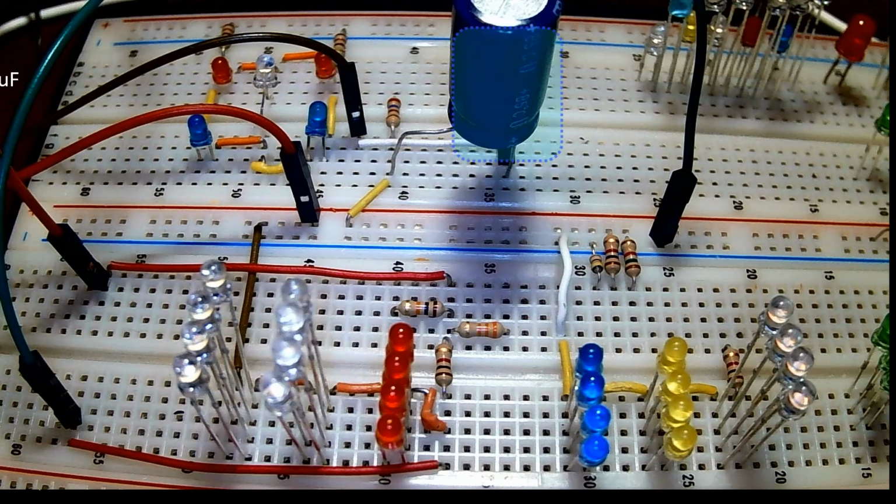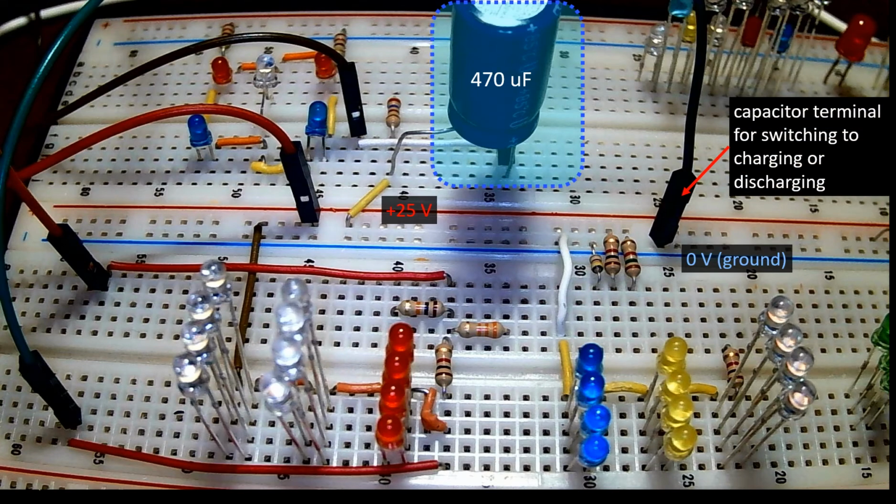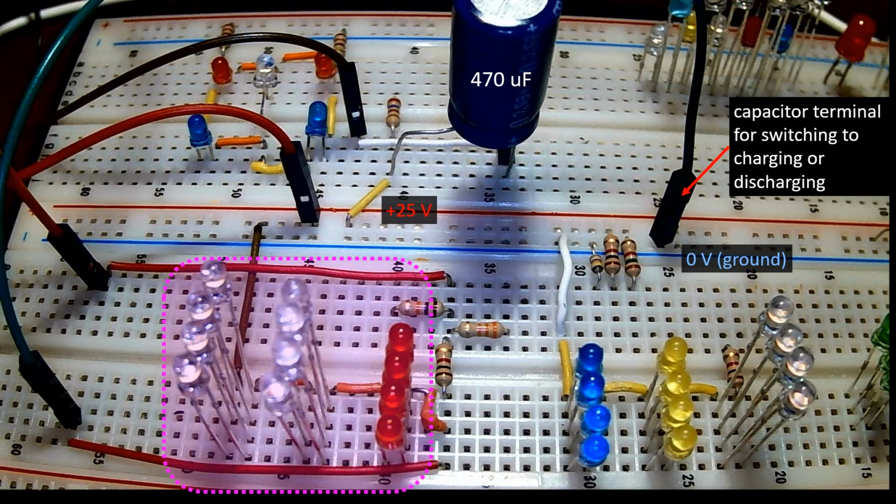The main element is the 470 microfarad capacitor, which you should have at least one. One terminal is connected to a 25-volt DC source. The other is a manually movable connector that can be switched to different positions on the circuit to charge or discharge the capacitor. In order to visualize the charging and discharging processes, one bank of 3 serial by 4 parallel LEDs is inserted in the current flow path for discharging,